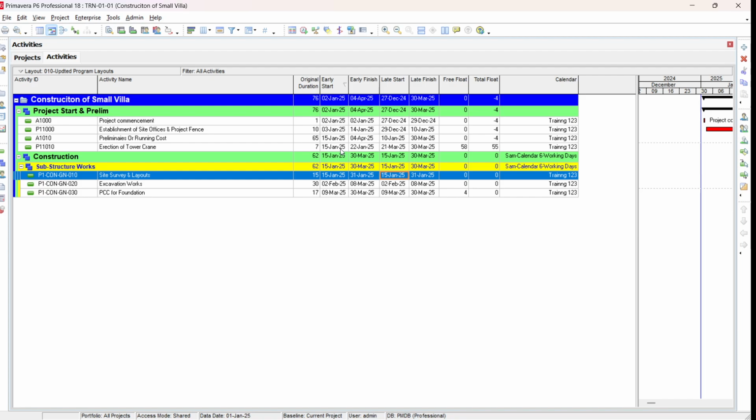So you can see here in this project. Okay, just 1 minute. Okay, something happened by chance, so I'll show you why. This total float for the project shows -4 days. So this -4 days shows that the project has delays, and the delay is 4 days. So minus float is showing you the delay in the project is a 4 days delay.